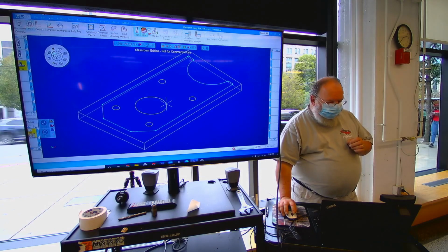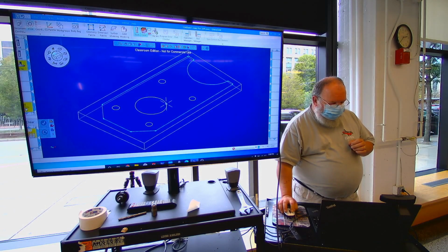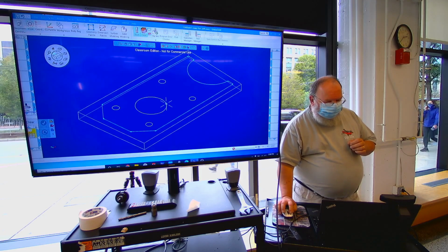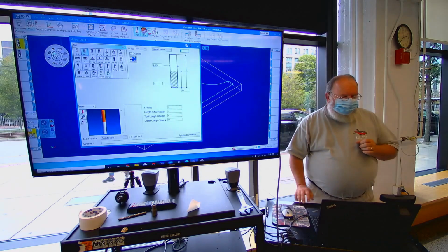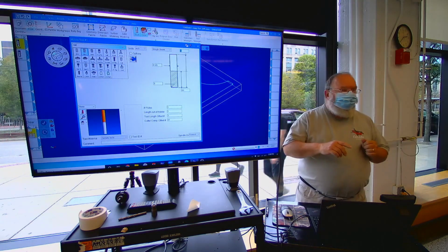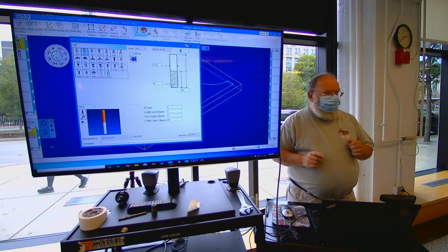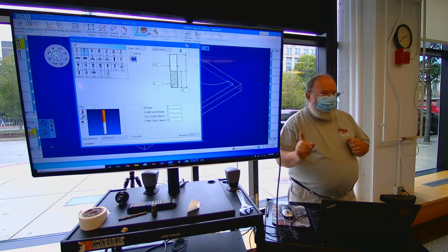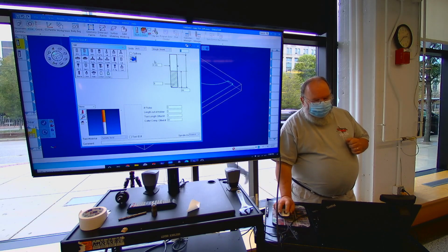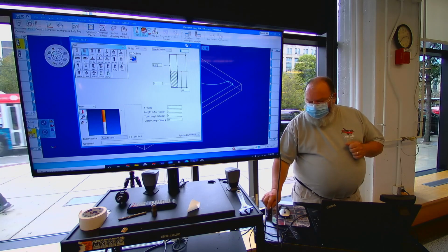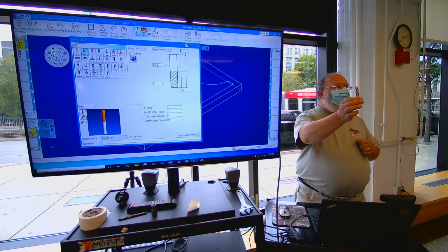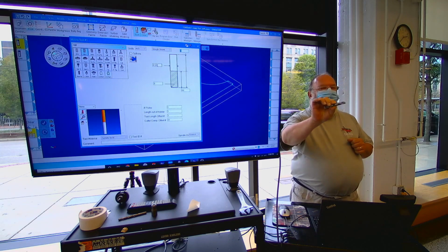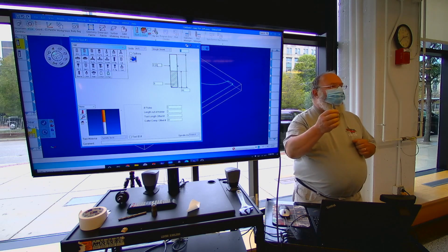The next thing I need is cutting tools. So I'm going to start with tile number 1, which corresponds to magazine position 1 in the machine, right down the line. Tile 2 is magazine 2, 3, 4, and so on, up to 20 in this machine. Tool number 1 is a 1/8 diameter end mill. For those of you who've never seen an end mill, this is a 1/2 inch diameter end mill. I'm not allowed to pass it around anymore. This is a 3-flute high-speed steel 1/2 inch end mill.